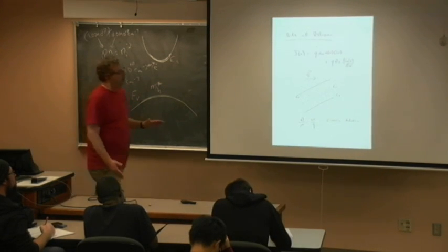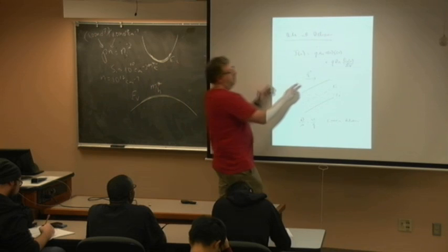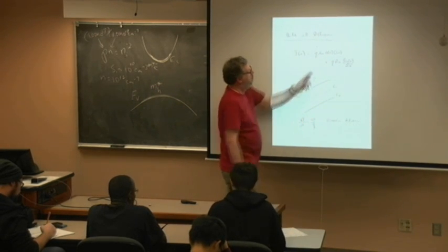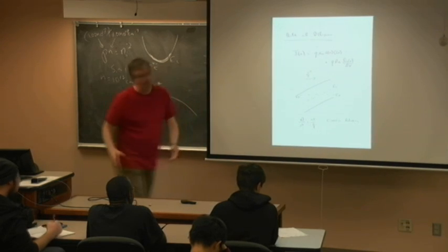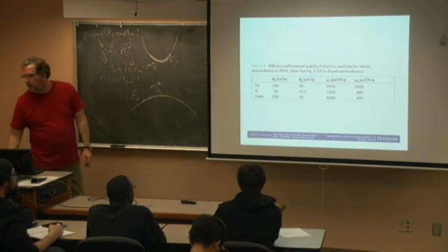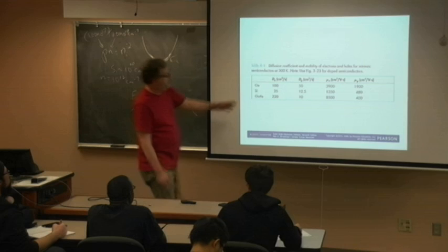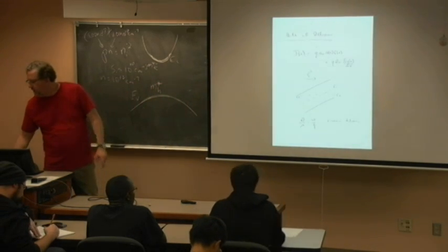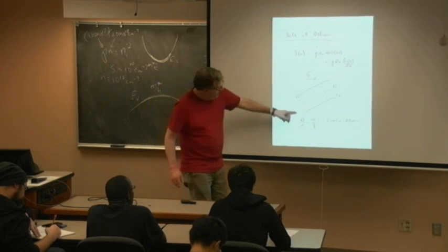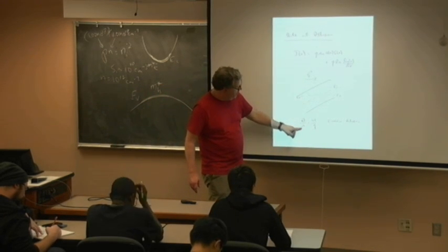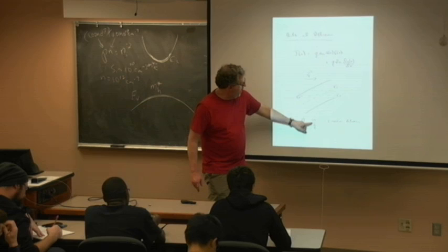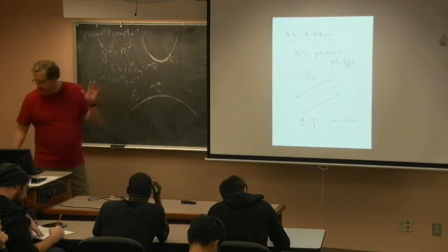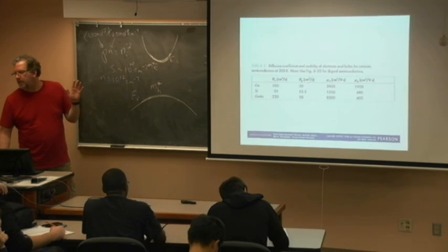So the electric field causes them to start to move with a certain mobility. And diffusion is tethered to that through the Einstein relation, D over mu equals KT over Q. My bad penmanship, sorry, I am a doctor, so I have bad penmanship.